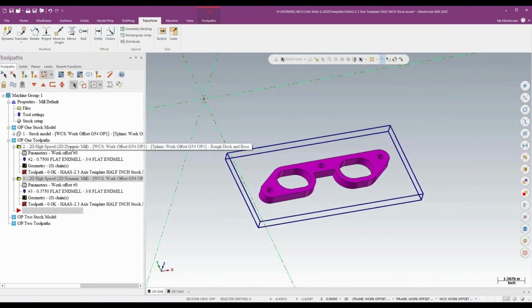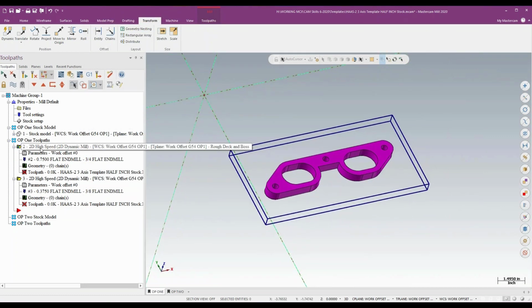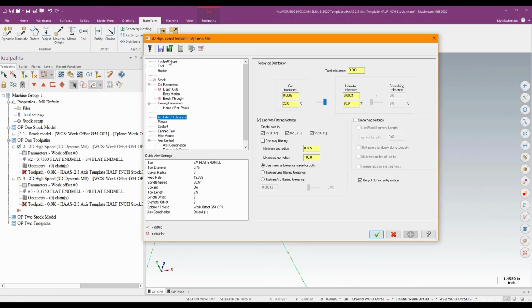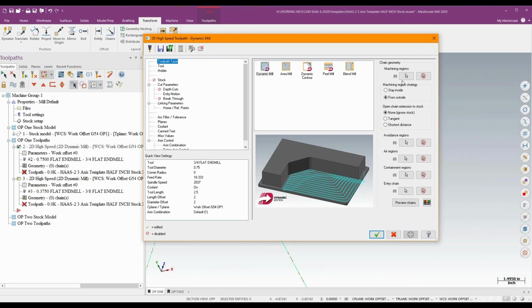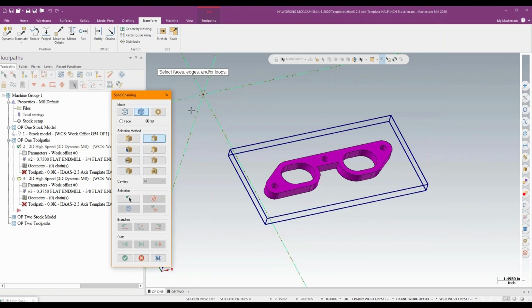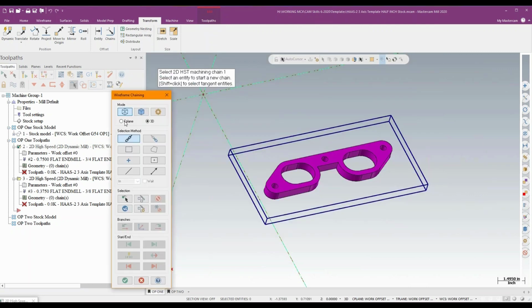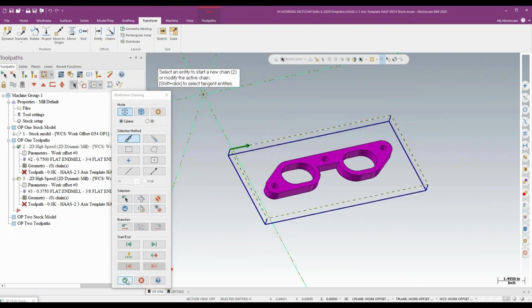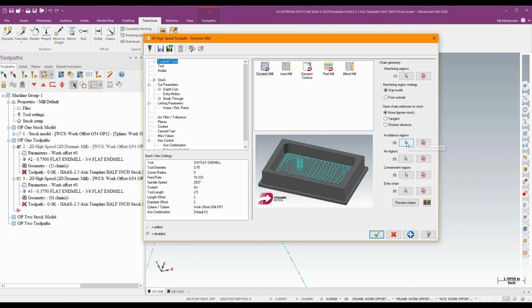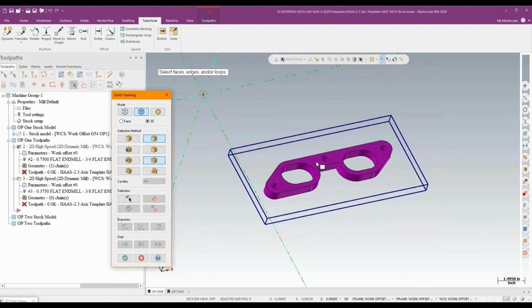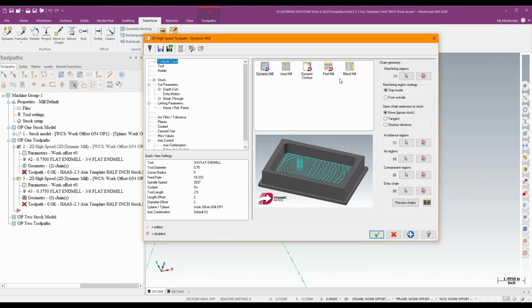All right. Now, this first toolpath is my dynamic. That's the outside one. So I'm just going to machine around the outside of the part. And again, I'm just programming it like I normally would, right? So from outside, oh, sorry, this would actually be an inside strategy. My apologies. So we'll do a quick chain around there, boom. And I'm going to have an avoidance region, which again is going to be the part itself.